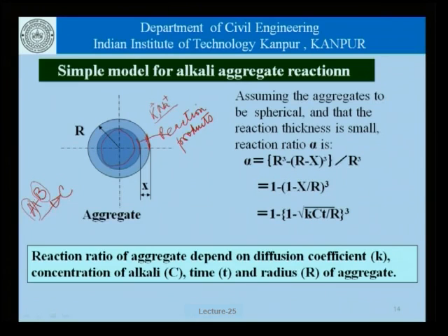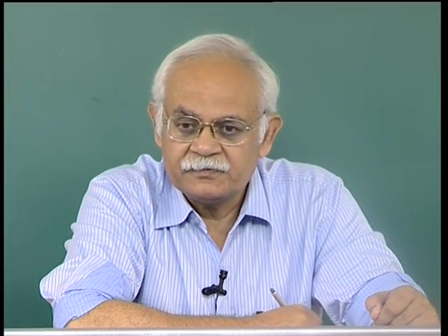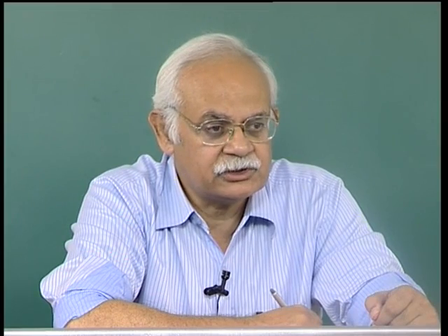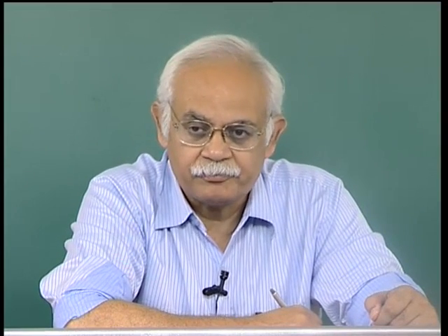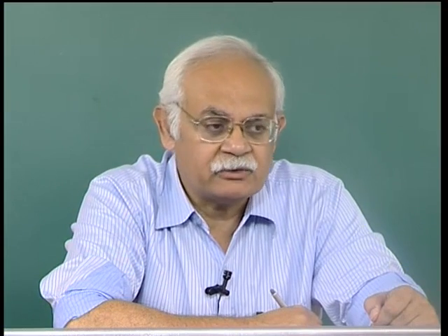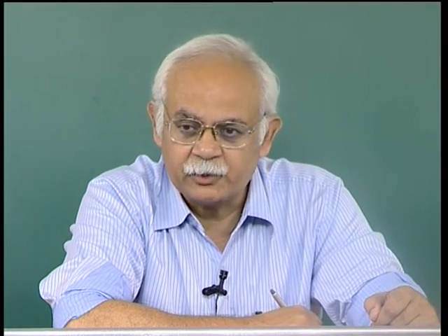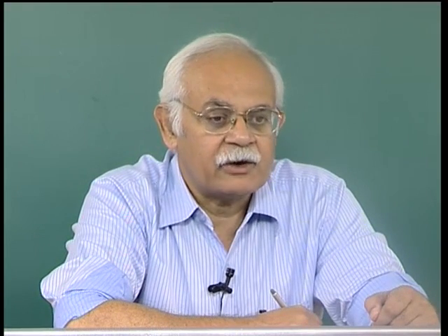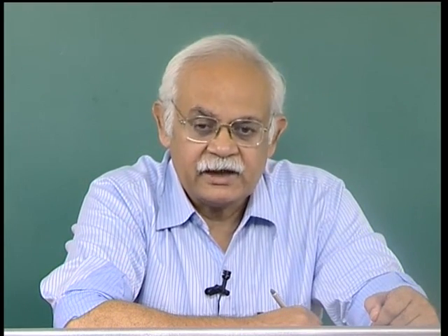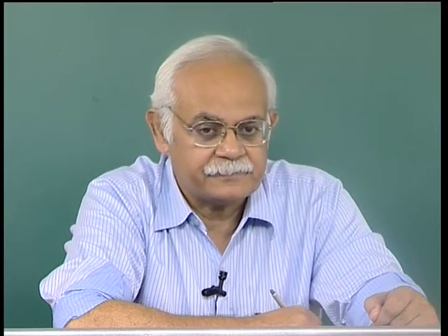So, in the scenario like that of alkali aggregate reaction, the situation translates to, do we run out of reactive minerals in the aggregate? The answer is pretty much no, because there are enough aggregates and therefore enough reactive minerals within the concrete for the reaction to go on. Do we run out of alkali metals in the pore solution? The answer could be yes or no, depending on what is the amount of alkali which is present in the pore solution to begin with, and that is related to the amount of alkali present in the cement and the quantity of cement in the concrete.